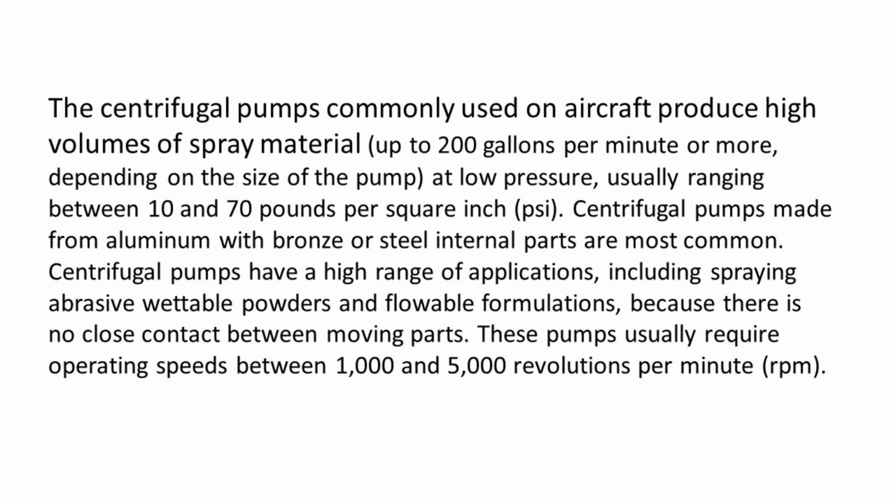Centrifugal pumps have a high range of applications, including spraying abrasive wettable powders and flowable formulations, because there is no close contact between moving parts. These pumps usually require operating speeds between 1,000 and 5,000 revolutions per minute (RPM).